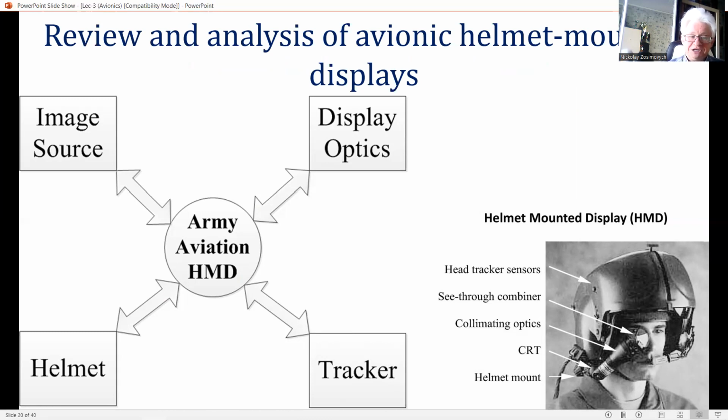FOVs of over 40 degrees can be achieved with a binocular visor projection system. The visor, however, is a long way from the eyes, and creating an extreme FOV is increasingly difficult over 60 degrees. The alternative IP system can give a larger FOV, but with a very high weight penalty. Also, a binocular HMD is inherently a better solution for night or poor visibility operation.